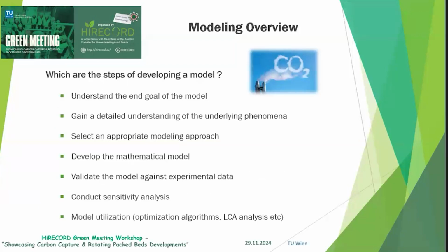The steps of developing an RPB model for carbon capture start with understanding the primary goal of the model. In our case, we have developed a model capable of designing an RPB in different conditions for industrial application. A model has to gain a detailed understanding of the underlying phenomena. For RPBs, we have incorporated phenomena to evaluate the centrifugal forces inside the reactor, the gas-liquid interactions, and the reaction kinetics involved.